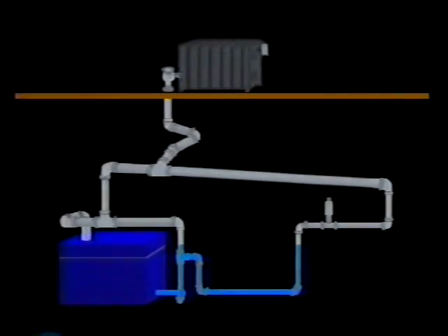With our understanding of near boiler piping, along with the purpose and need of each pipe, let's now take a look at what system piping consists of and the significance of its elements. We'll begin by examining a basic one-pipe system. Notice that the near boiler piping is connected through a T in the header into the system riser, then tied into the existing main.